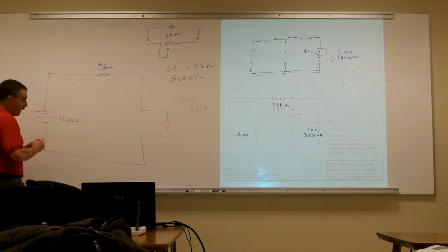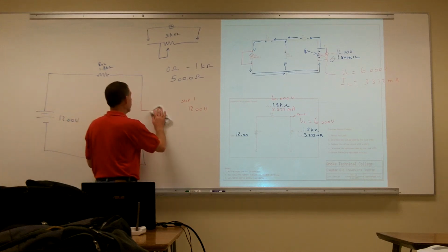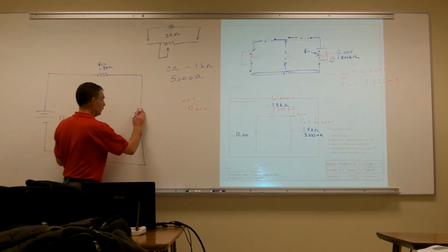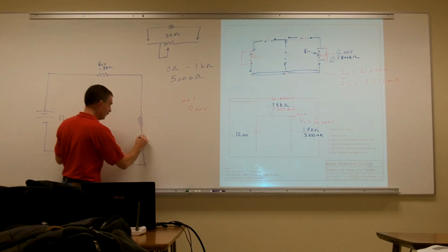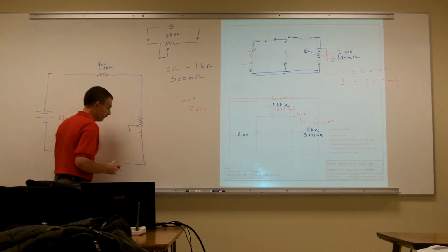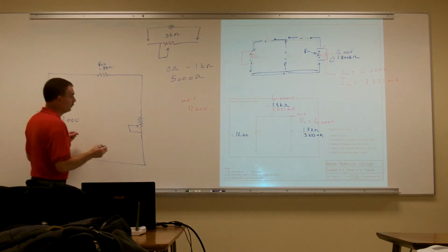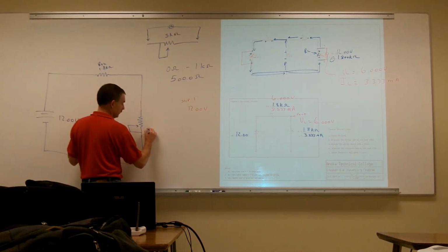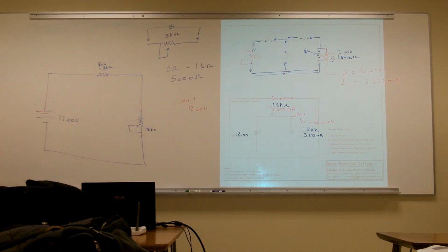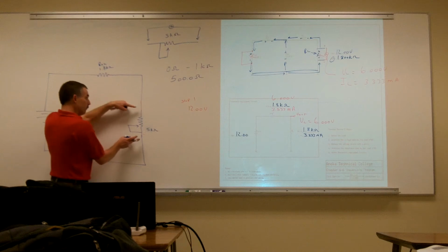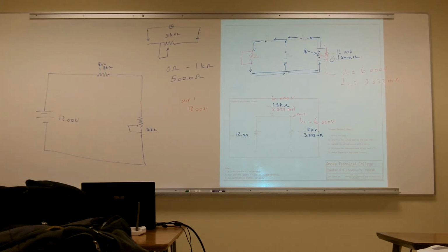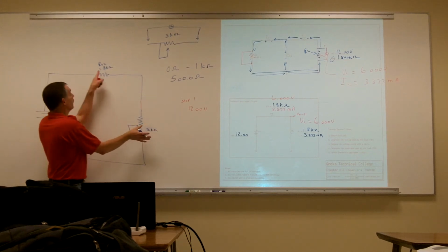That's step 1. Then I'm going to put in a variable potentiometer and set it to five kilo ohms. I'm giving it the maximum amount of resistance to begin with. So between my rheostat and my Thevenin's resistance, which one's going to take the most voltage? 5K. This thing's going to take almost twice as much as this one.